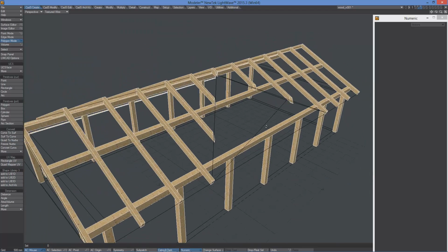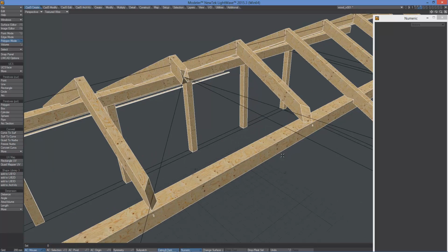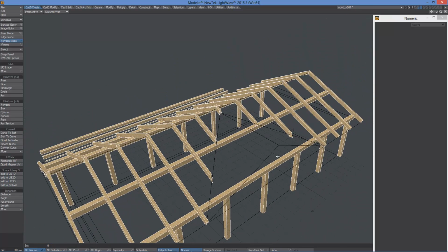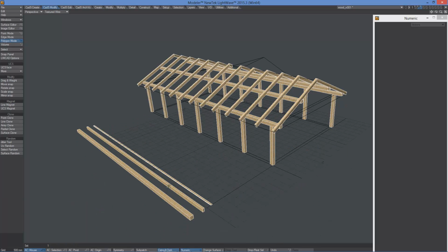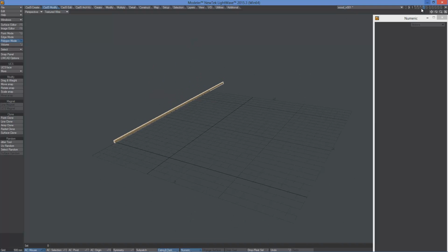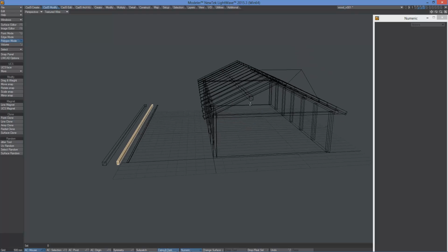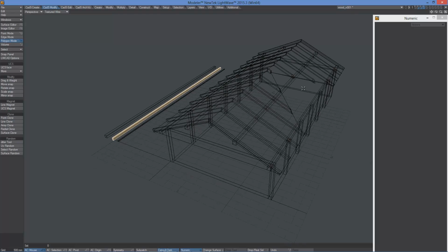This is a little bit more delicate operation. To continue with this side roof, it is better to move to another empty layer. Select the roof beam object, copy and paste into another empty layer where we will continue. We also need to set as background viewport the previously cloned object and our helper object, the building object, which we use for automatic UCS.